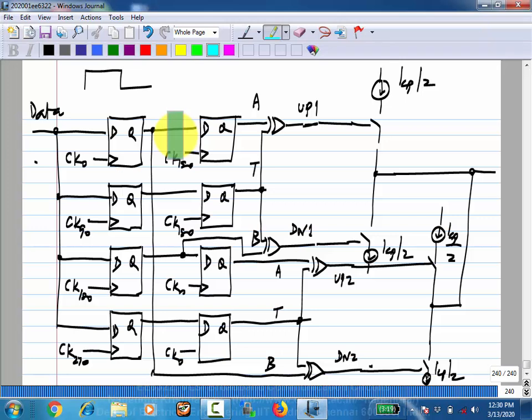I mean, this kind of thing usually makes sense if you cannot comfortably make the full rate, or you have to burn a lot of power. Like I said, you take any circuit, whether it is analog or digital, you can go on increasing its frequency by burning more and more power. And at low frequencies, meaning at frequencies which are comfortably possible in a given process, the power dissipation or the current consumption usually increases linearly with frequency.